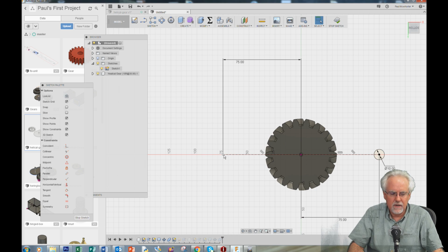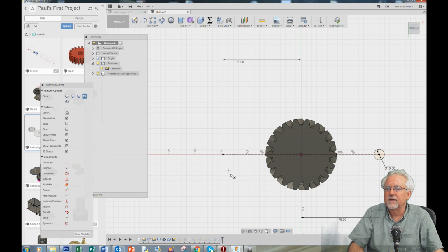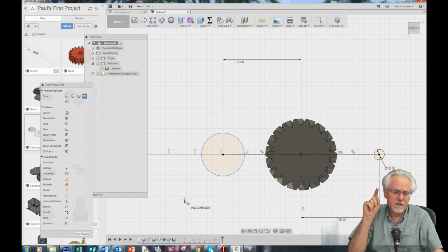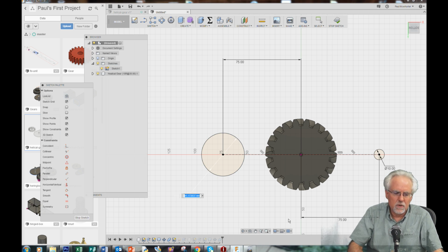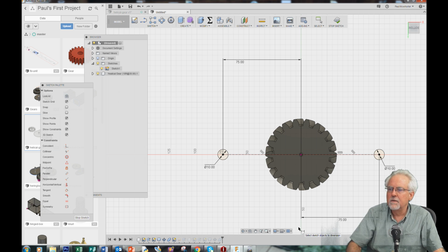What do I want here? I want a circle. So C. Hover over, let it snap, click once, pull out, click again. What do I want to do? Dimension it. So I tap D on the keyboard, got my dimension tool, come here, come out, and what do I want to dimension that? I want to dimension it at 10. Okay? So enter, boom.